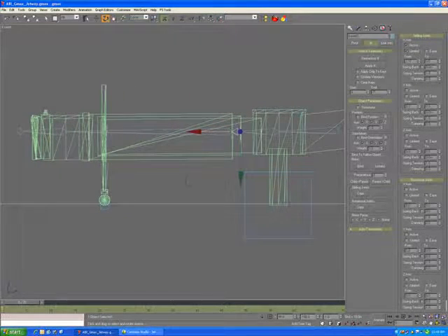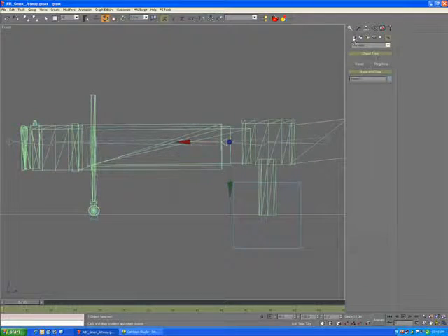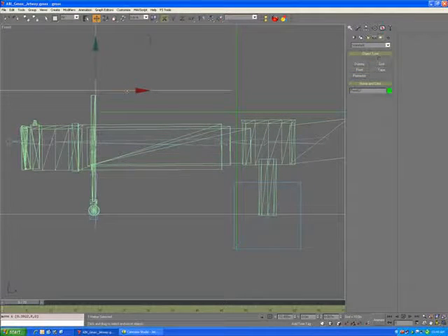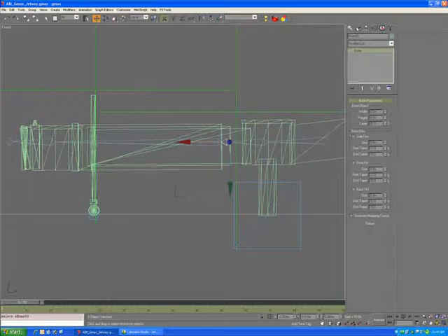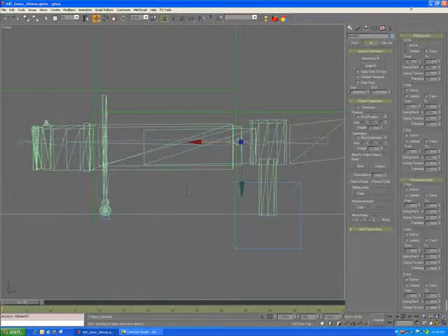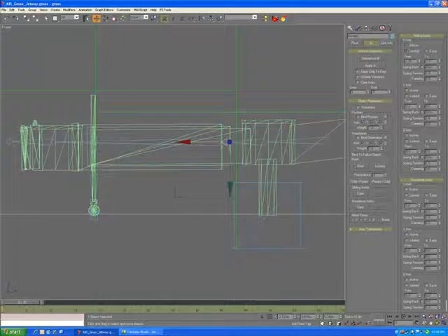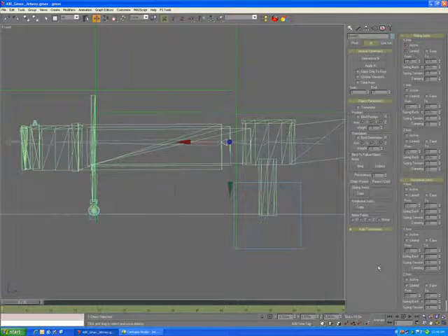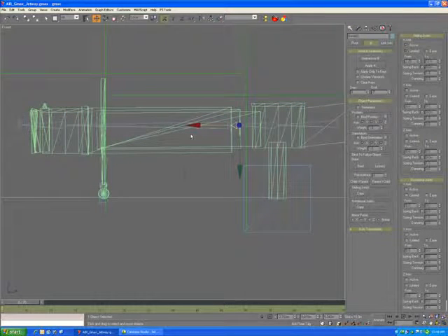So what you can do, if you want to, is put markers in. So if we go in here, we can put a point in, say, there. That's the farthest, and then a point in, say, here. That's the farthest that it should go. And then this will allow you to have somewhat of a guess of what's going to happen here. So we're going to go from that point, and then we go to the second one, and we go all the way out to roughly that point, give or take. And there you go. So now you have that sliding joint set.